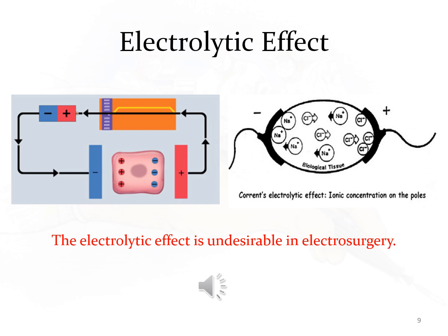With direct current and low-frequency alternating currents smaller than 5 kHz, the electrolytic effect dominates. Ion migration takes place in the tissue. Positively charged ions travel to the negative pole and negatively charged ions to the positive pole, which gives us electrolytic damage to the tissue.